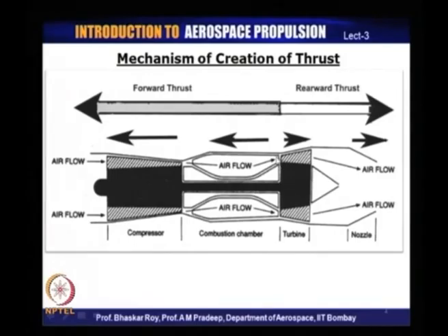So, the air mass would exert, again from fluid statics, a certain amount of pressure through the body of the turbine, and that exertion of pressure or force, a net pressure over the entire area, would be a force, and that would be in the backward direction. So, the turbine essentially produces a backward force while operating inside an engine.